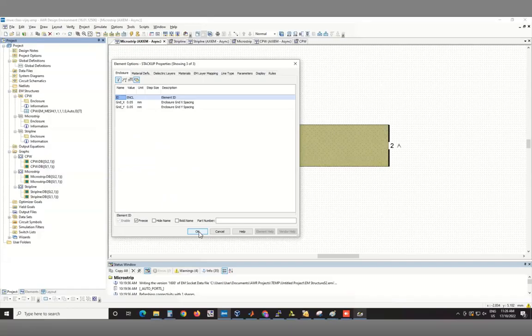This is a very standard technique in any numerical methods, because you always have to choose some step size, either in spatial dimensions or in time dimensions if you're solving some kind of a differential equation. And how do you choose the optimal step size? Because the finer it is, it's always better. So it's a compromise between accuracy and the time it's going to take to solve. Same way here.